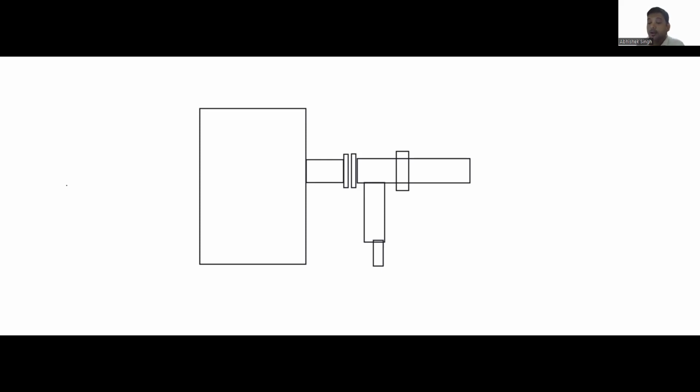Clear? Now, to find out the maximum allowable nozzle load, the normal sequence is that piping does the stress analysis based on where they have provided the supports and the thermal expansion value, and they give us the nozzle load. That is the actual procedure which should happen. Here it happened in a reverse way, Abhishek. Yeah, I'm coming to that, why it happens like that.